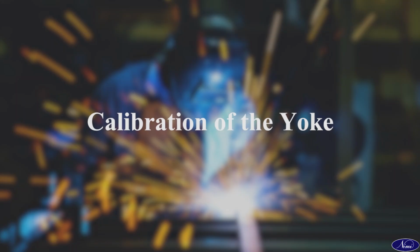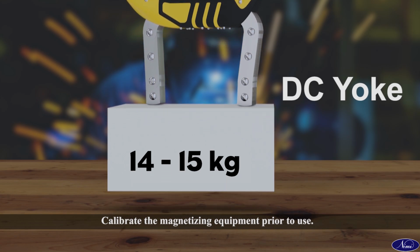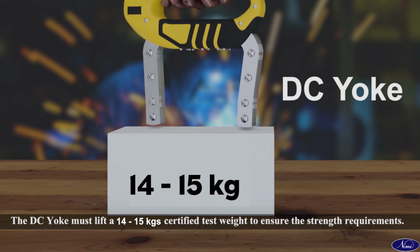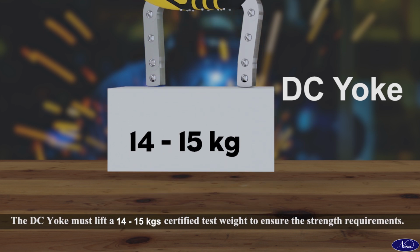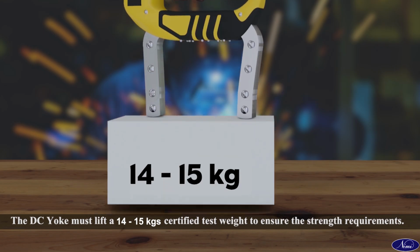Calibration of the yoke. Calibrate the magnetizing equipment prior to use. The DC yoke must lift a 14 to 15 kg certified test weight to ensure the strength requirements.